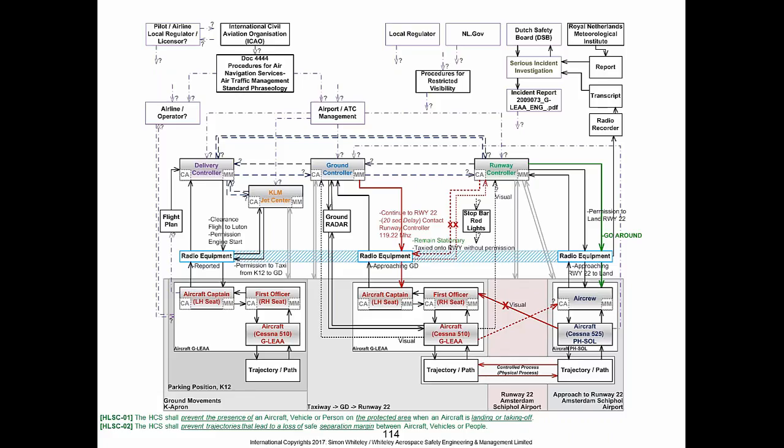Now, from an ICAO perspective, if there is a standard airport equipment fit, that says your airport shall have these things fitted, one of those standard fit things might be, as Shem pointed out, stop bars and the runway status lights.